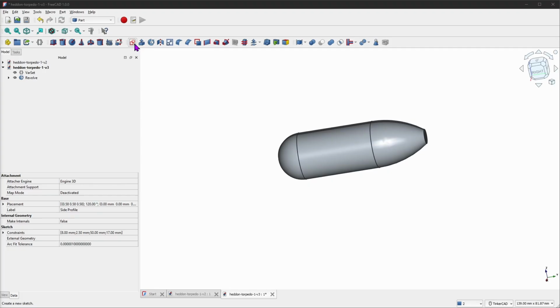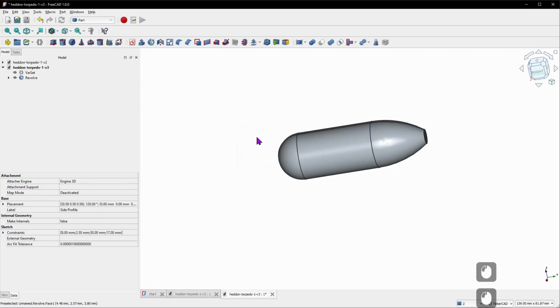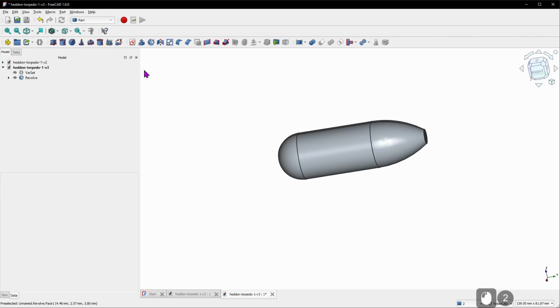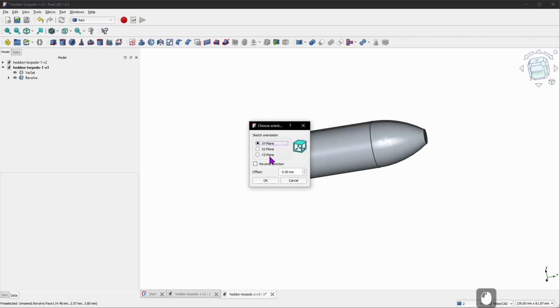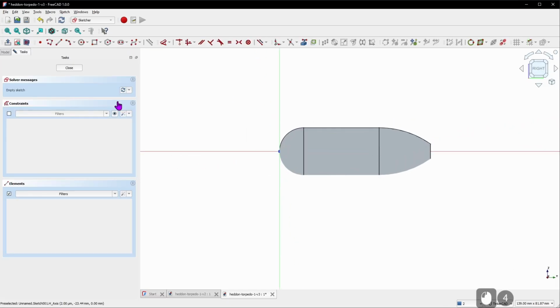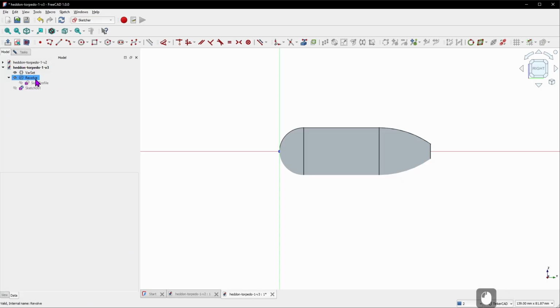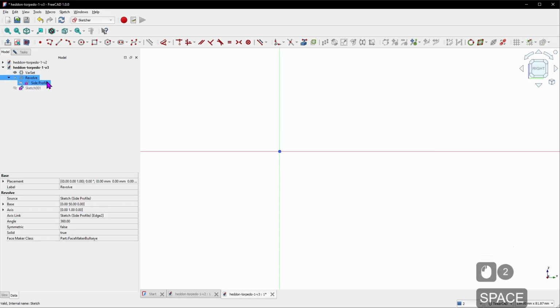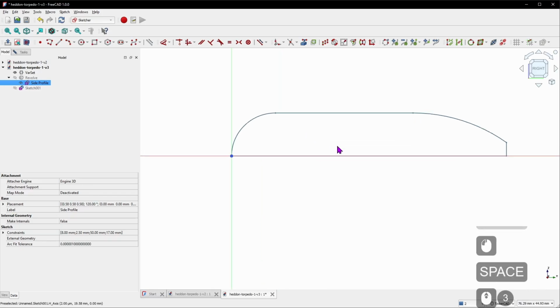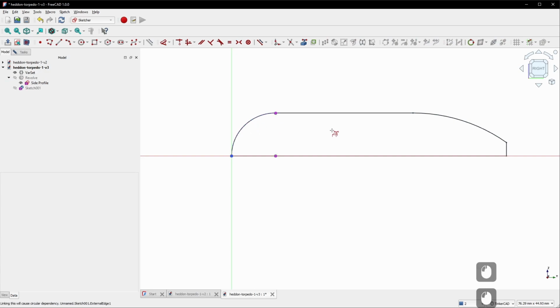Let's create another sketch on, oops, I'm going to deselect everything by just clicking in the space here. We're going to create a sketch on the YZ plane once again. I'm going to go over to the Model tab and click the Revolve and hit the space bar and bring the profile back so that I can grab some external geometry. We want to use that tool to get the front and the back of the lure. And now it's time to drop some lines. So we're going to drop a line here. We're going to drop another line here, a vertical line, and a line here.